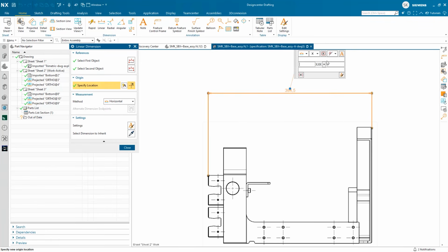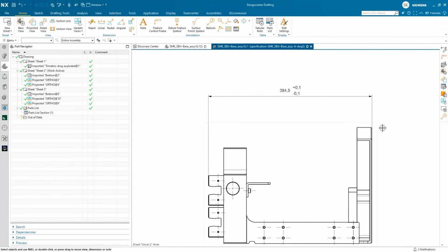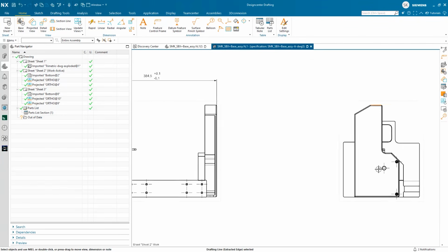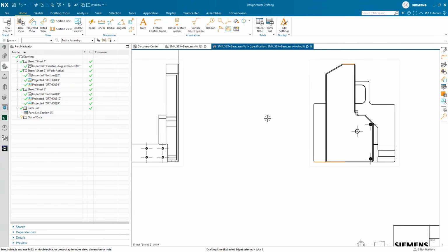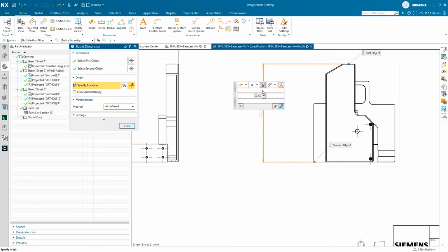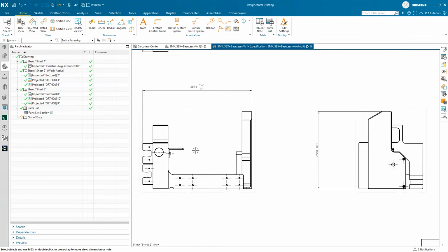In this case, I want to add some tolerance, making sure that some options are available. So I can come in there, add some of the tolerance and specify what the tolerance may be. That's how I go about creating these types of assembly dimensions that I can utilize for the assembly of this subsystem in any situation. I want to do that first, and then when I am done, I'll come back and do the same thing at the detail level, creating detailed dimensions as well.